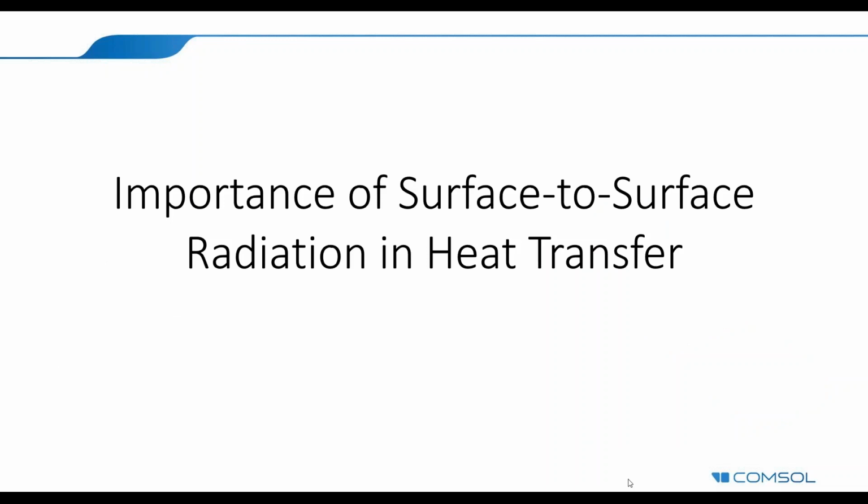Okay, so this part is really important, I believe, because sometimes surface-to-surface radiation, the radiative heat transfer, is not included in models, and it should be. It leads to an inaccurate estimation of the temperature distribution. So really, the point here is to try to identify the conditions that make thermal radiation and surface-to-surface radiation important to predict the temperature distribution. I will not cover radiation in participating media or absorbing media in this webinar, as we have enough content for today, but that's another field that is also covered by simulation with COMSOL Multiphysics.